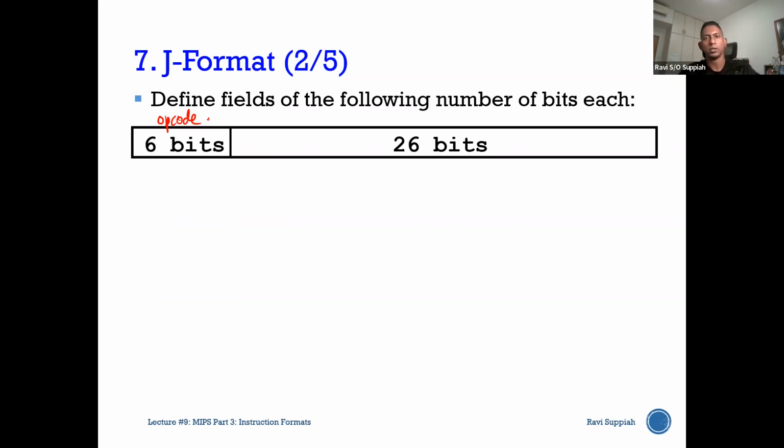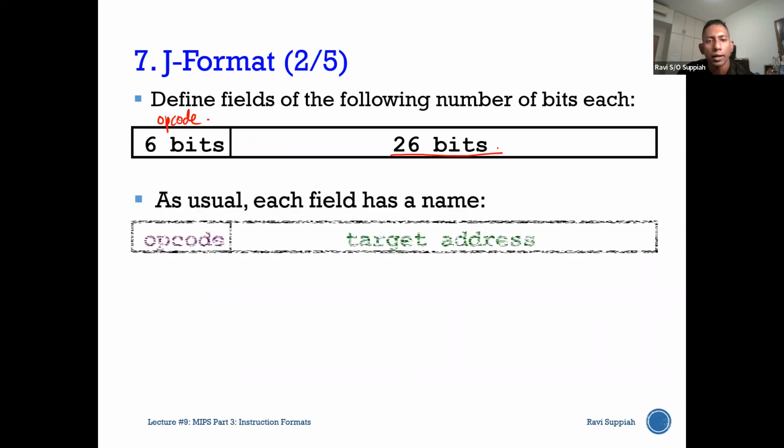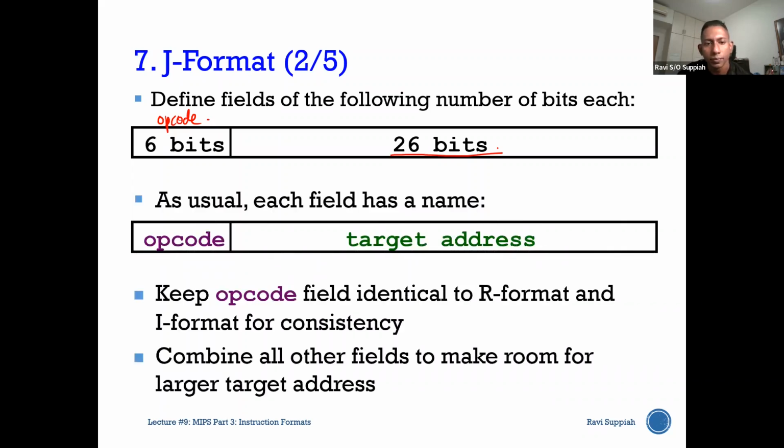So I need 6 bits to specify the opcode, which means I will never have 32 bits free to specify an address. The only number of bits that are free for me to specify an address are 26 bits. So I have 26 bits left to specify an address. How can I translate these 26 bits to 32 bits now?